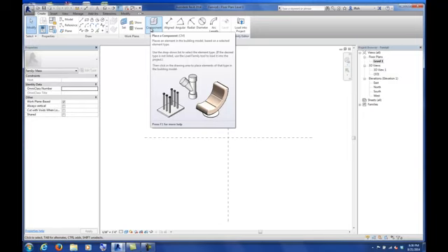But for now, we're just going to click on circle. You should be able to find the circle up here. It's the one at the top right of this draw dialog box. And I'm going to go ahead and left click. I'm going to make sure I snap. And just like in AutoCAD, you get that intersection snap where you've got a little purple X. I want to left click there, and that's at the origin. And I'm just going to draw a circle. It doesn't matter what the radius is. I'm just going to draw it out and then left click again.